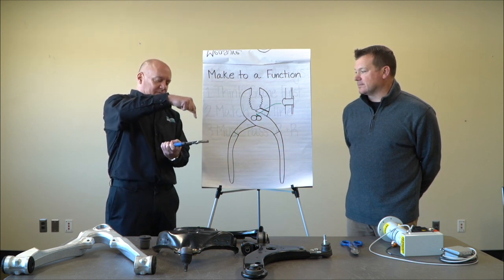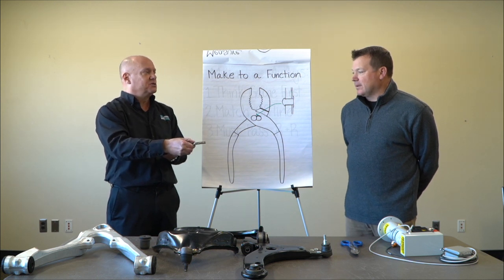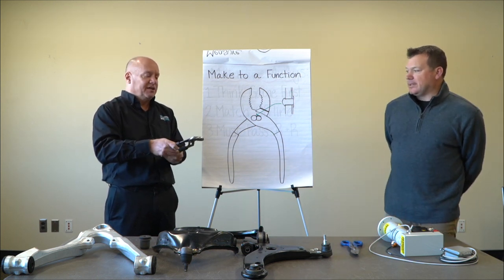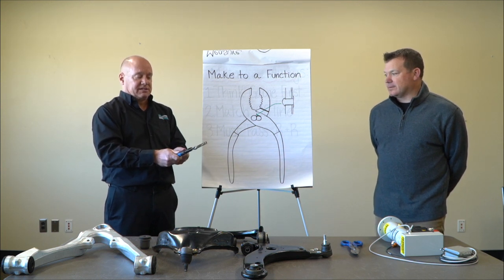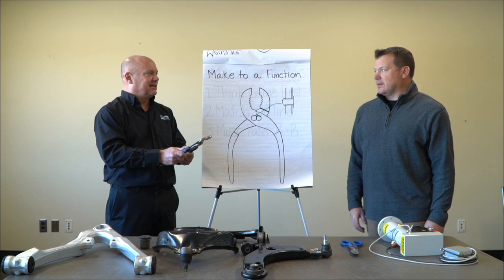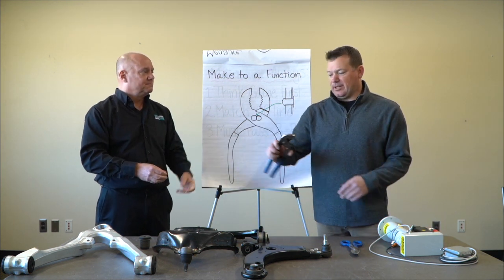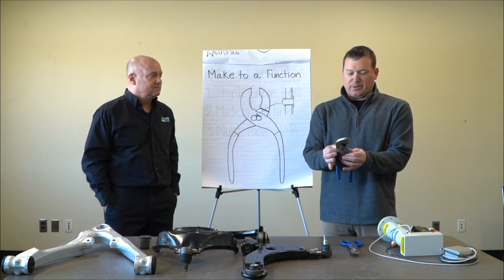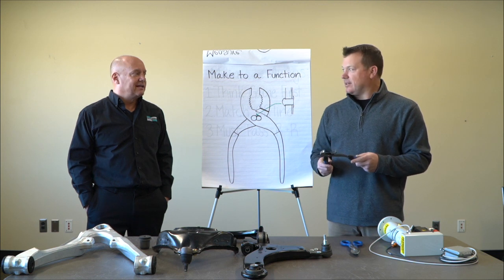You could have a press to exactly the same height every time, but because of the way the metal flows, because of part tolerances or whatever, you'll get different actuation forces. Really, all the people care is that it's a tight, not a sloppy fit, but it's workable. And it's unrealistic to think you're going to machine and make precision parts for a tool that gets thrown around and used every day. Cold heading a rivet is not that accurate either.